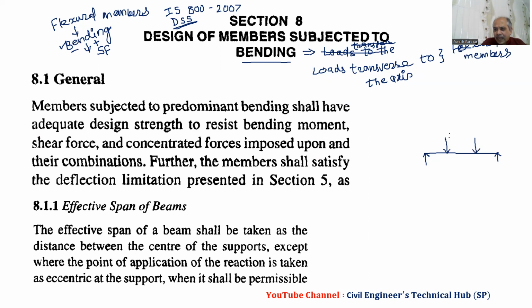Now we can have a member in pure bending, or in shear plus bending. If we have a beam like this, the reactions are the same because it is symmetrical. Say the spans are L/3, L/3 and L/3. If we draw the bending moment diagram, we have PL/3 constant in the middle, and this portion is pure bending. Why is this pure bending?